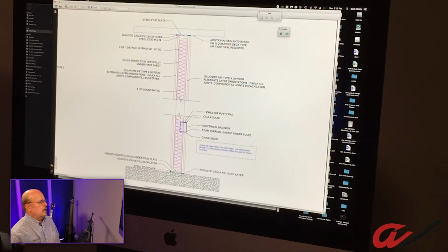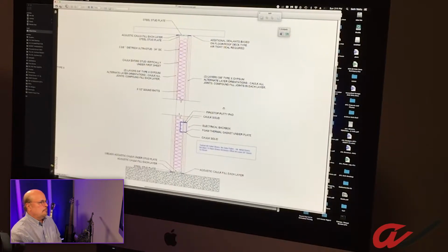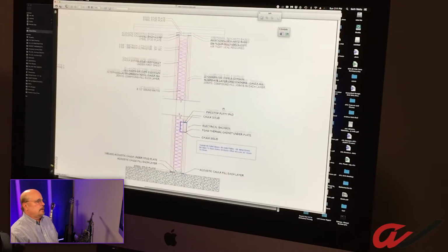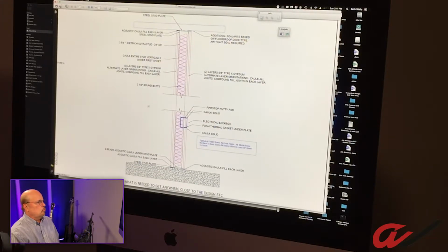We also like to have them use caulk in between layers. We like to have an X pattern of caulk across the sheet and then a layer of caulk 1 inch off the sheet on all sides. It just tends to dampen a little bit. Now, the weird part is if it's screwed in properly, that'll all flatten out a lot. But it does, in our experience, help a bit with some of the variances in walls.